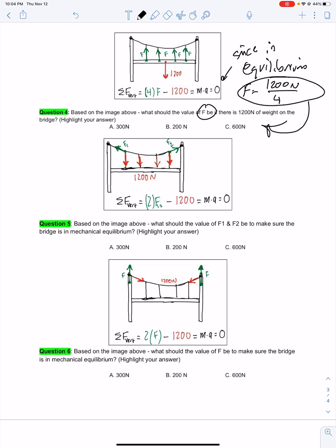All right, if we look at our bridge slightly differently, now we have our tension here that had been supporting our weight. If we take a look at it from the point of view of the overarching rope, now we have that tension being reacted upon, and so we have 4 red weights down, and those red weights are all adding up to that same 1,200 newtons, and so the overarching cable needs to be able to support that, and that's F1 and F2.